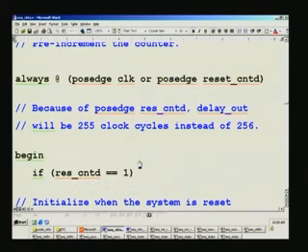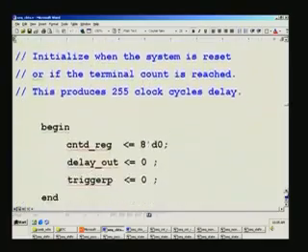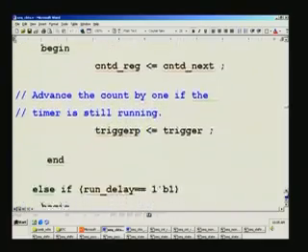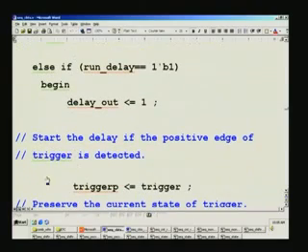In earlier way of representation, this has been separated out. This power on reset has been dealt here, and the actual counter reaching 255 had been dealt somewhere here in between. So it added one more else if, thereby slowing the system, and also instead of 255 set point we got 256.